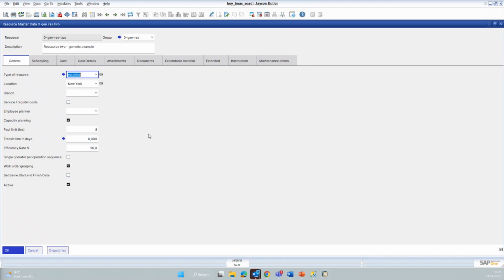The pool functionality means you have a guy on the shop floor, you connect a resource to this guy, and the guy will see all the work on this resource for the next 8 hours. So all operations available on that resource, because every previous operation has been finished, for the next 8 hours will be available. Why 8 hours? That's again completely up to you. For me, that's the typical time of a shift.